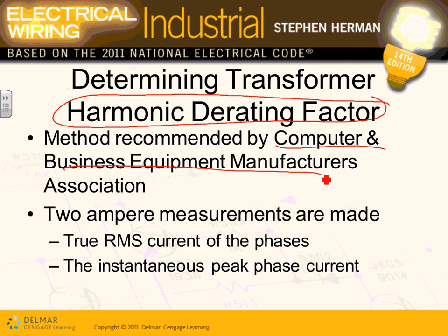So those guys also recommend to derate the factor. If you have a transformer, Adam, that can carry 100 kVA, if that transformer is feeding electronics, they derate it down to 70 kVA. Who cares? So instead of pulling 100 kVA out of a transformer, the manufacturers say, why don't you pull just 70% so you don't overheat it? Okay.